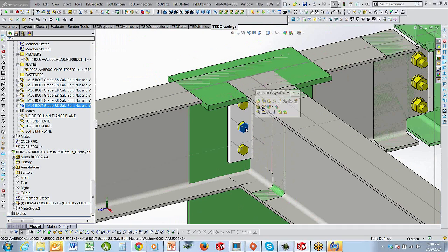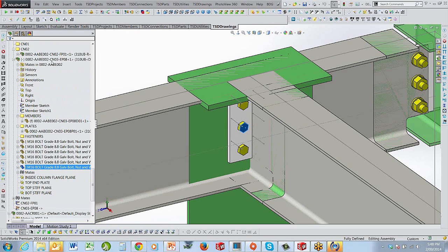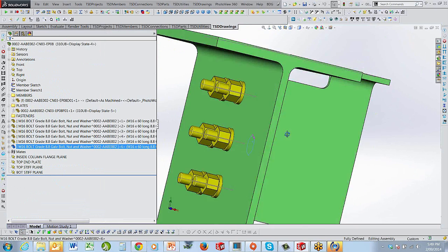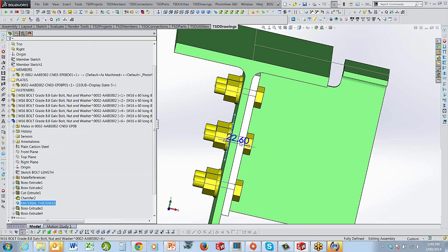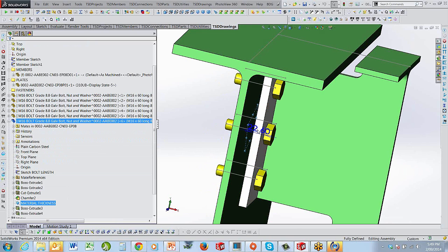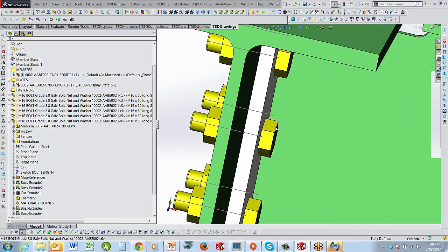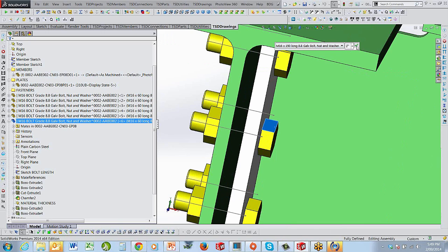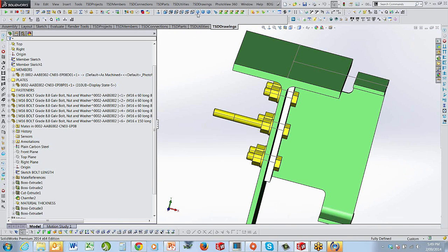Okay, that's fasteners. Fasteners are quite simple. And as I said, they are virtual, so that there's no external files. They're actually kept inside the assembly that contains them, and the lengths and material thicknesses are manually adjusted unless you're using 2015. So you can actually change that dimension there to be whatever you want it to be, and you can change the configuration of the bolt just by going in and selecting the config. Something extraordinarily long if you wanted to. And you can group the whole bolts by grabbing them all and changing them all at once.